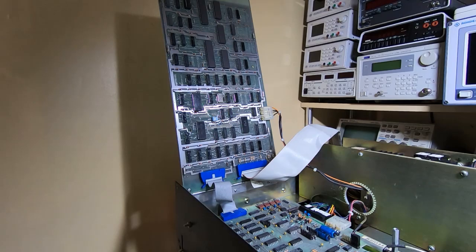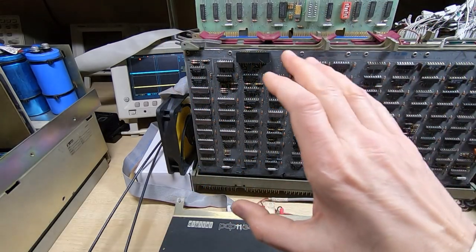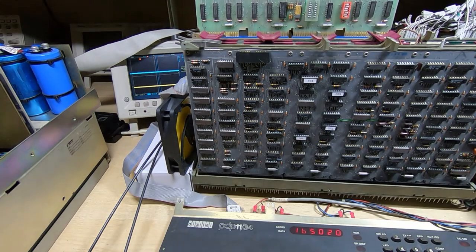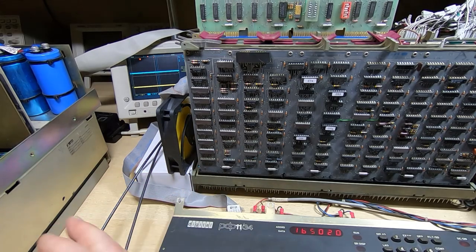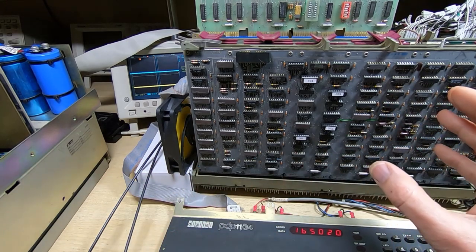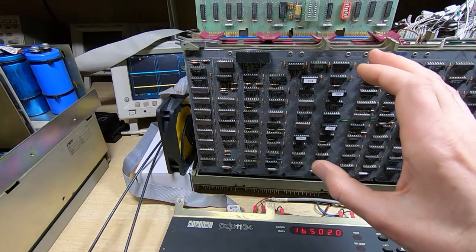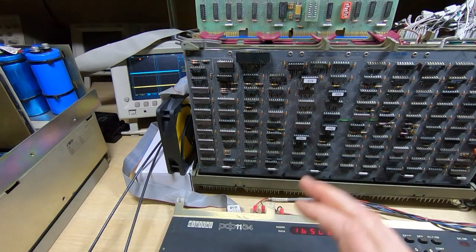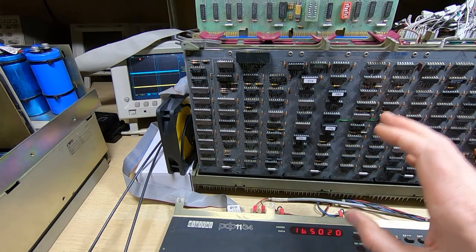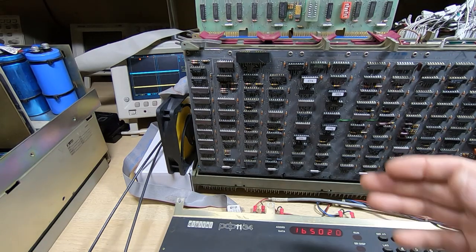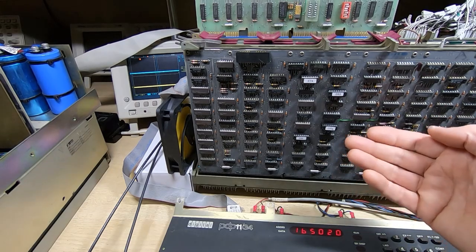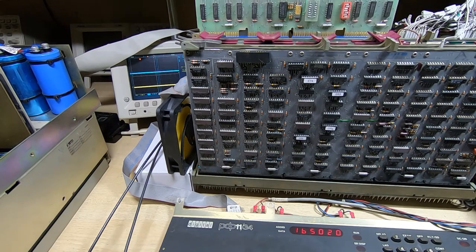So I'll just move the camera back. The problem we have is, as I said, where to start looking when we get a fault like this. You can either work from the floppy drive back or from the PDP forward. And I tend to go from the PDP because we've already worked on this and we're reasonably confident at least some of it's working, but we don't know what the state of the floppy drive controller is. So if we can get the machine itself to give us a bit of information as to what might be going on, then it would be helpful. It might make our life easier.